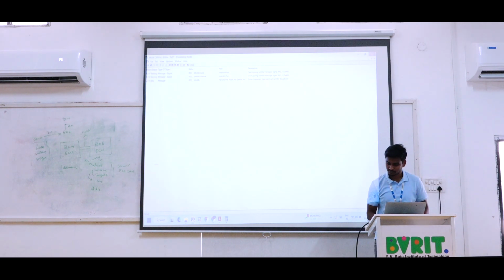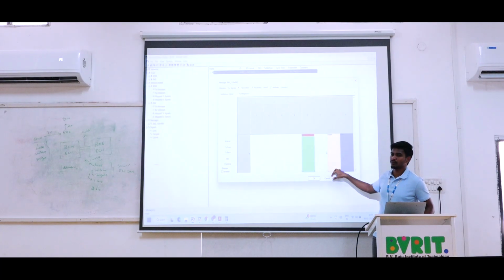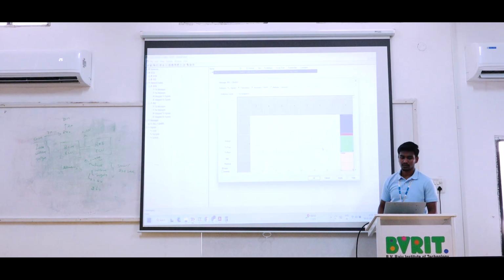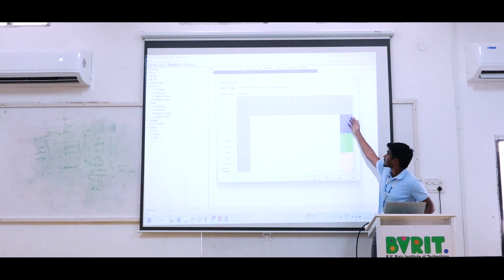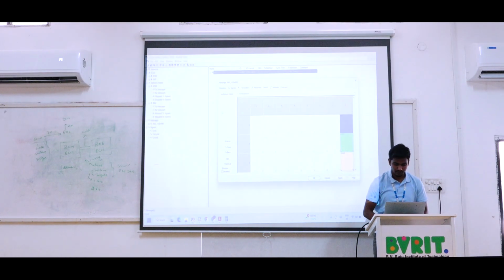Okay. So I will open the layout and move the signal values. Instead, I will arrange each signal as an individual byte: first byte for lock, second byte for unlock, third byte for tailgate. Here it shows that the value starts from the 0 to 7th bit and 0 to first bit.